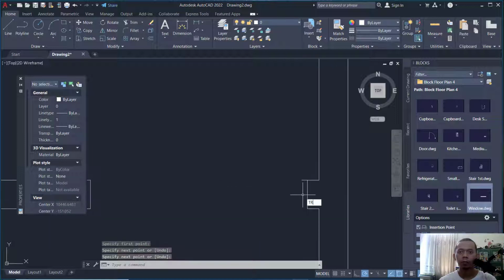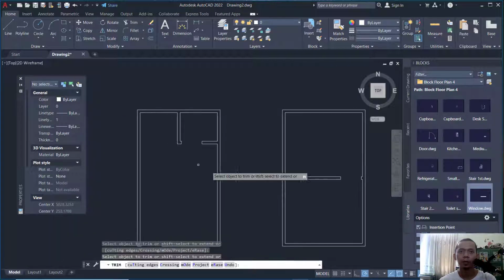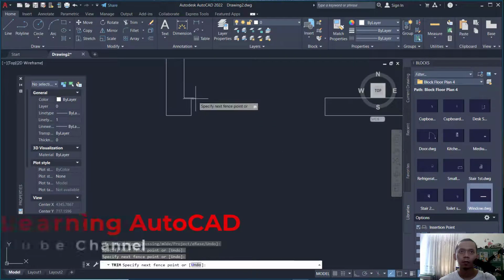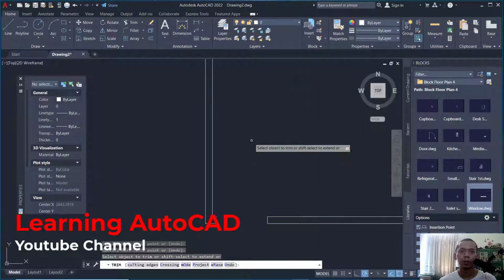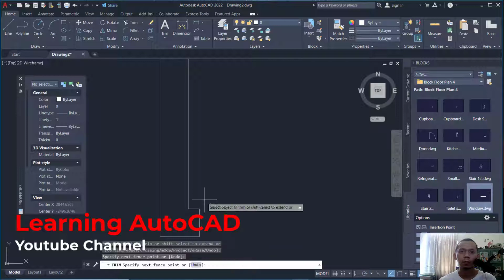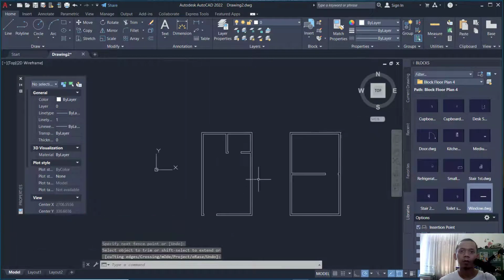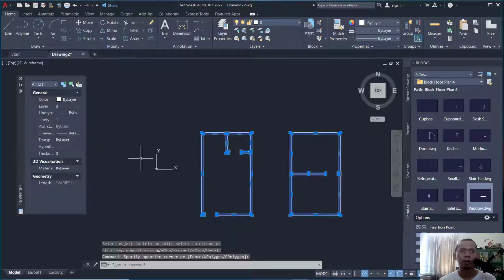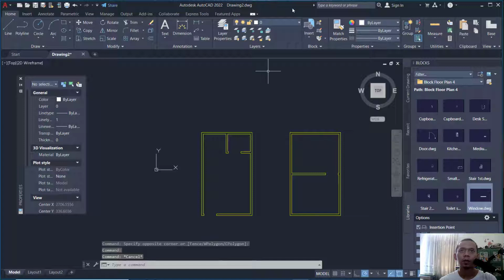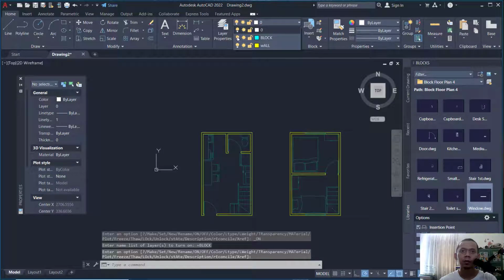Okay, you can trim this line object. Okay, and in the bottom here. Now we can convert all these objects into wall. You can click here, layer, and set into wall. It will be changed into yellow. You can also activate the black layer again. Click on this icon, so it is automatically active.